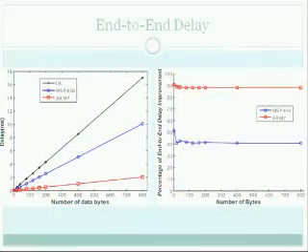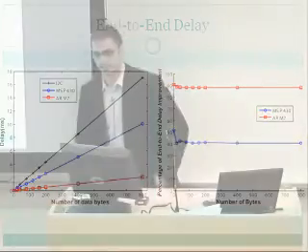Now, this whole architecture has been implemented in Verilog HDL, and it has been mapped into two different components of a single family of Xilinx CPLD, which allowed us to have this actual bus implementation running at maximum speeds of 68 megahertz or 45 megahertz. Having the ability to map this to actual hardware allowed us to use the mPlatform to move on and evaluate and see if we actually met the design guidelines. Yes?